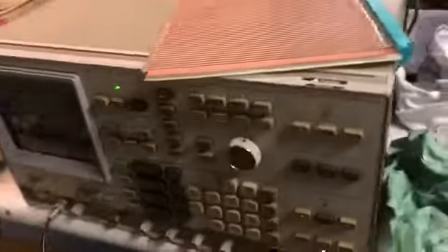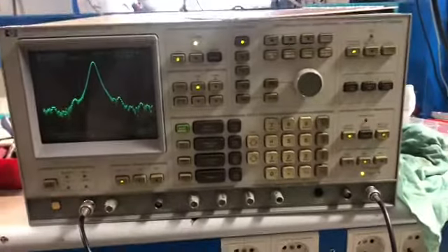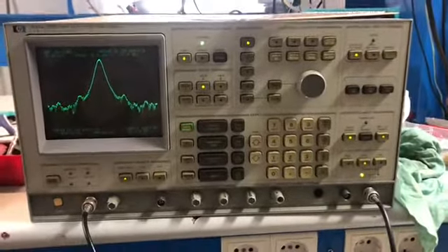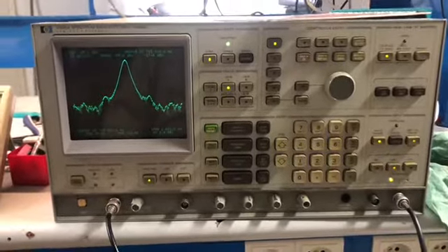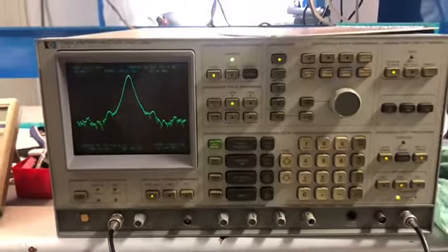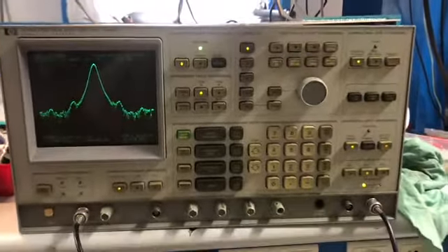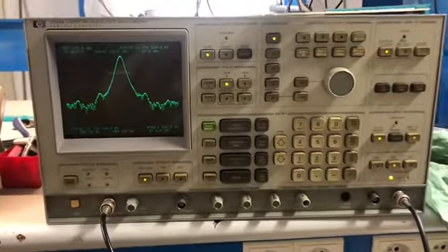And for sure, without this signature analyzer, it was impossible to understand the problem of the instrument, because in the service manual, in the troubleshooting section, there are several tables with all the codes that should be read with the signature analyzer, and without it is impossible to trace the problem backwards.